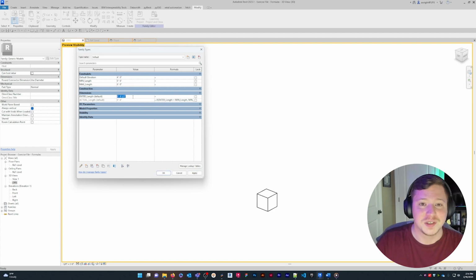Revit formulas are a powerful way to make dynamic parametric families that can be altered at the push of a button. Instance-based families with well-thought-out formulas are often more intuitive to use and easier to manage than huge typed catalogs and endless duplication of types during the design development phase. Formulas can also make a family abide by the rules of a real-world product, such as minimum and maximum sizes.